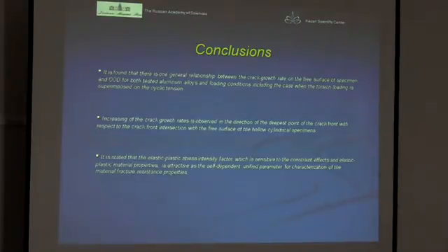So, the conclusion of my talk. It is found that there is one general relationship between crack growth rate on the free surface of the cylindrical specimen and crack opening displacement for both tested aluminum alloys and loading conditions, in the case of tension and torsion cyclic loading. An increase in the crack growth rate is observed in the direction of the deepest point of the crack front for both tested aluminum alloys. And it is stated that the elastic plastic stress intensity factor, in my opinion, again, is a very convenient parameter to present for interpretation of crack growth rate data. We take into account plastic properties of